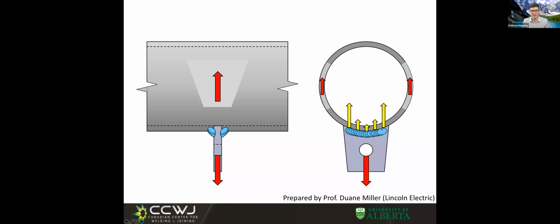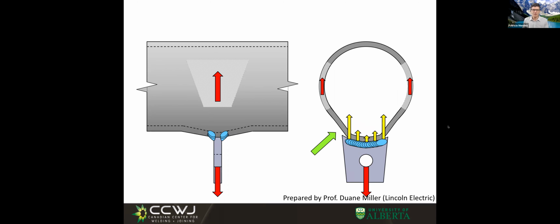In this case of the weld, the start and the end are going to be subject to stress concentrations that maybe were not obvious when we first thought, right? We just think it's a plate on a pipe. And we don't see the pipe deform with our eyes. We don't see this kind of light bulb shape deformation. But it is there. And the metal is very sensitive to deformations that are invisible to the eye. And that is how it cracks.